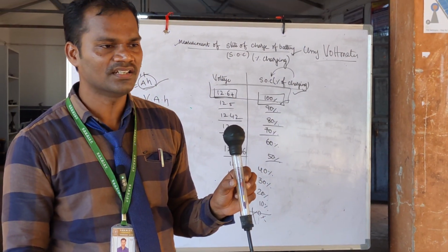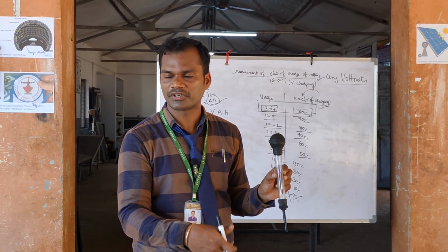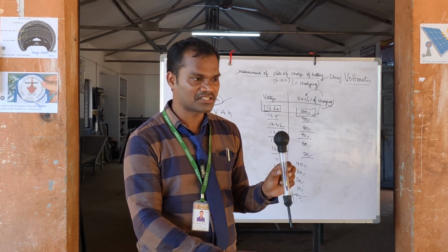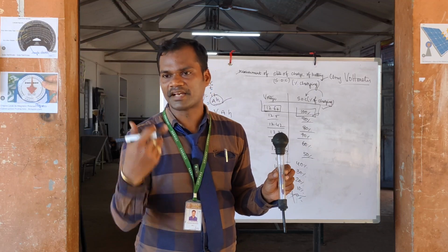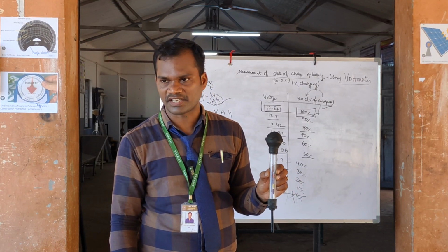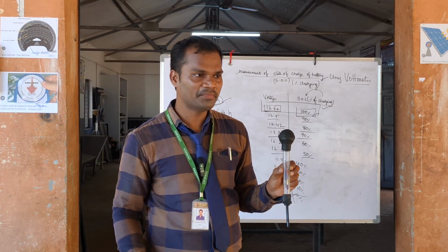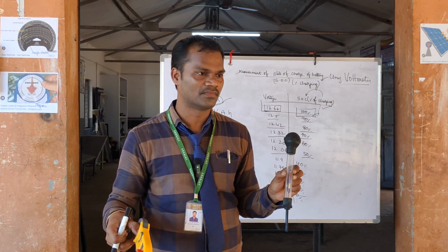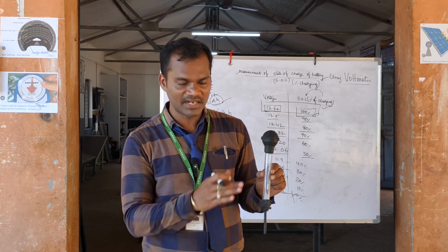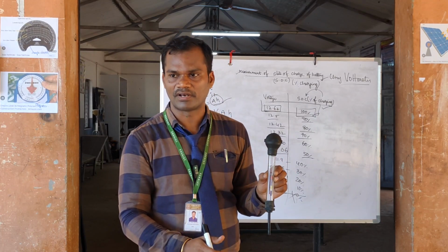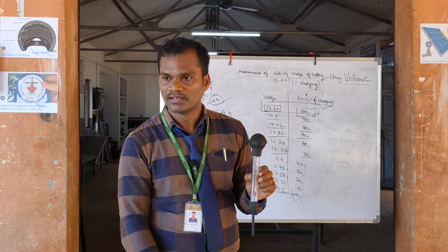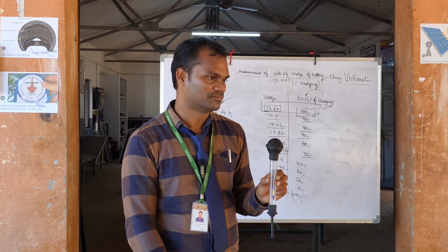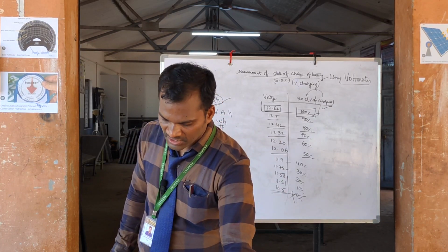and as per the battery tester, we have to keep it charging again. And what is the life of the battery? Already around 50% of its cycles have been completed. The voltmeter is giving a good value. Why? Because it's an instantaneous value. Why? Because it's a no-load value. This is a loaded value, and this is also the water level value. Water level is low and battery health is also weak. So this is the outcome for the battery.